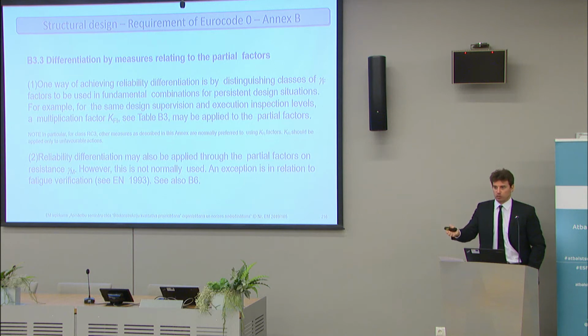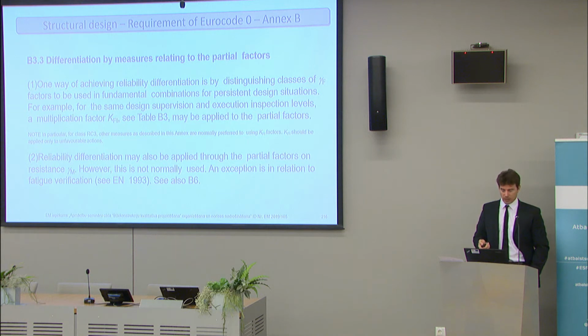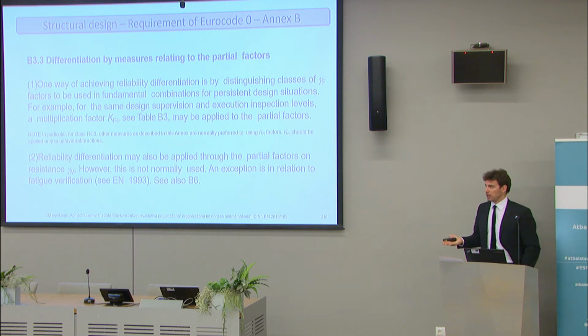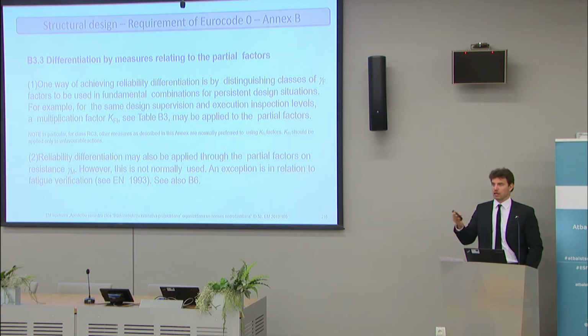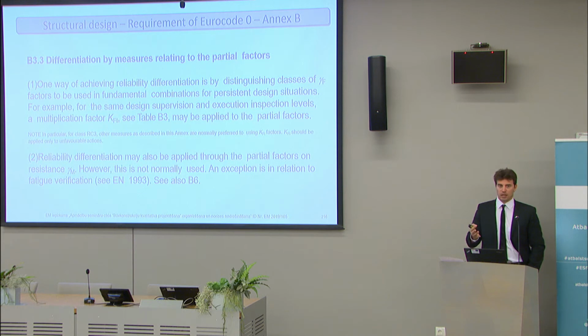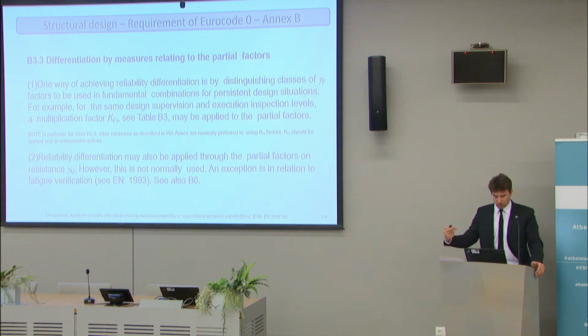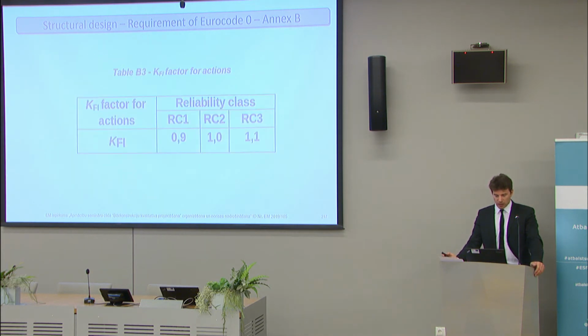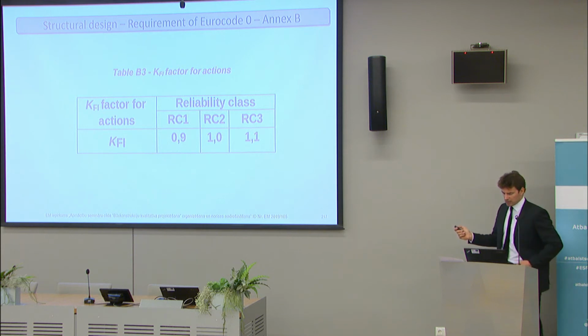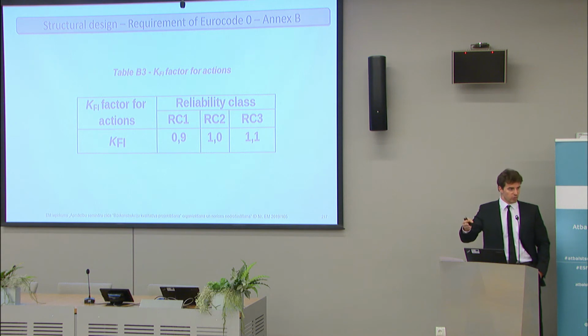Assume that you are able to compute the variance and the characteristic value of your material. So you have, of course, to make experimental tests, but there may be companies that have some kind of material, like for wall buildings, that do that, and then they also provide a material parameter that designers can use in their calculations. Here, I didn't show it maybe yet. These are these K_F1 parameters associated to the reliability classes that are also related to the consequence classes.